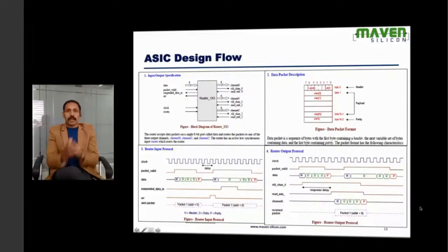Because the chip is a digital component, it can understand only the binary. You can't drive any packet or frame. Then you have to convert the packet into binary. So are you going to drive something like bit per clock cycle or byte per clock cycle or more than 1 byte per clock cycle? That's what the protocol defines. So these are all the important things.